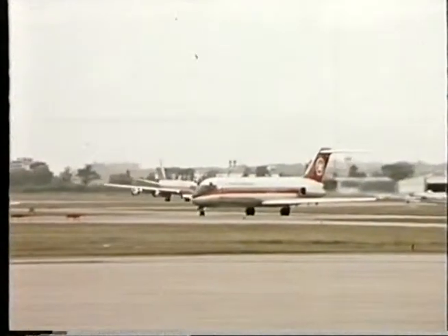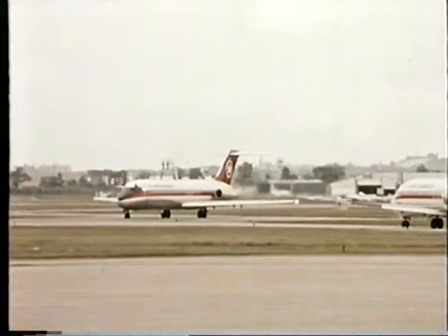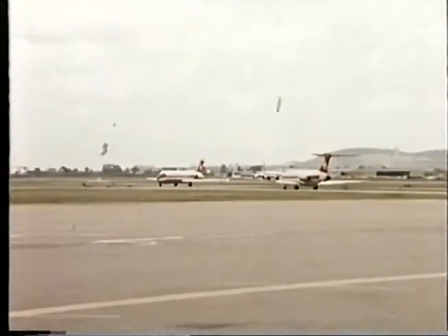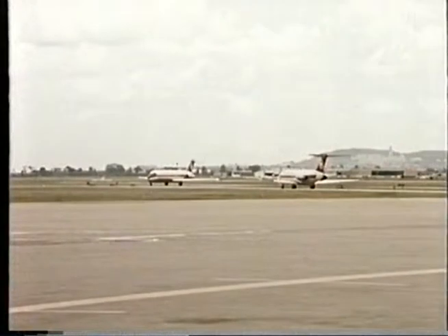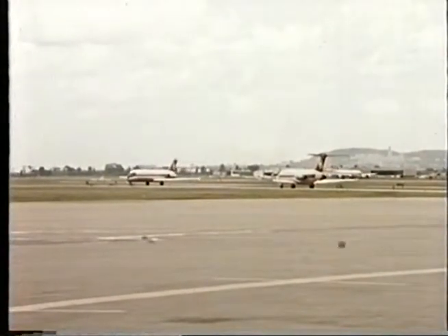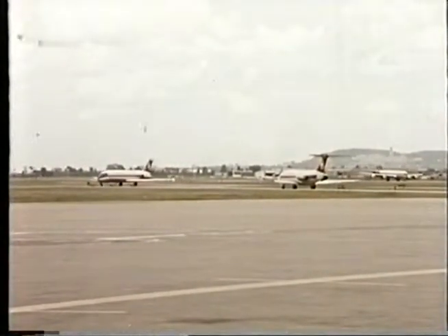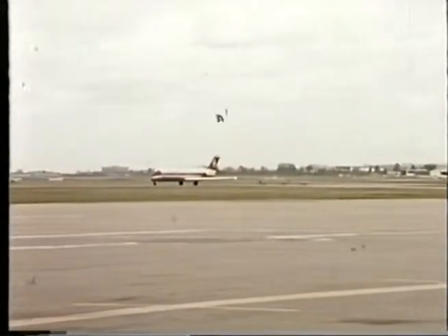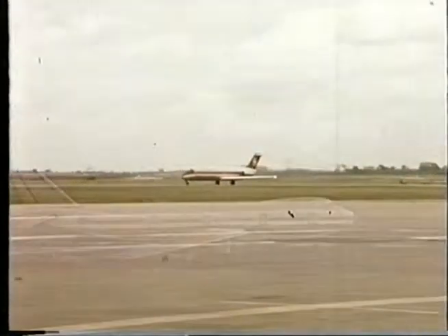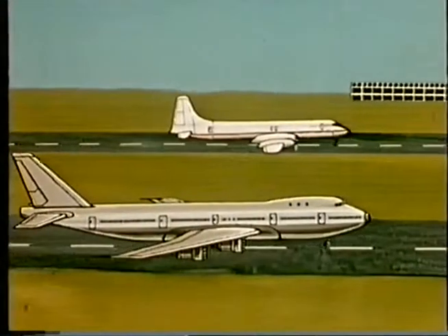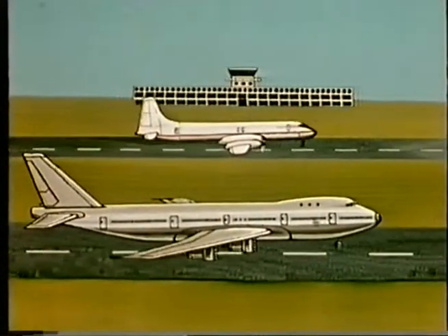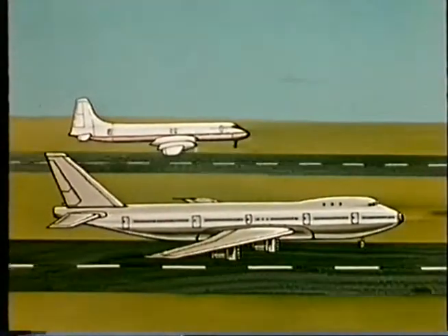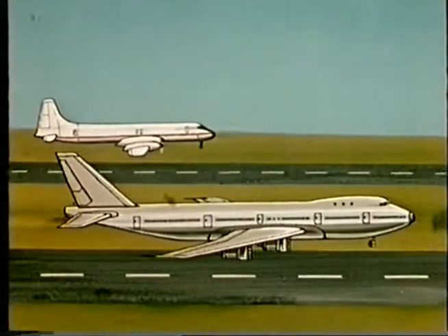Aircraft forming part of the aerodrome traffic shall be controlled to provide the separation minima outlined, except that aircraft in formation are exempted from the separation minima with respect to separation from other aircraft of the same flight. Aircraft operating in different areas or lanes on aerodromes equipped with runways suitable for simultaneous landings or takeoffs are exempted from the separation minima.